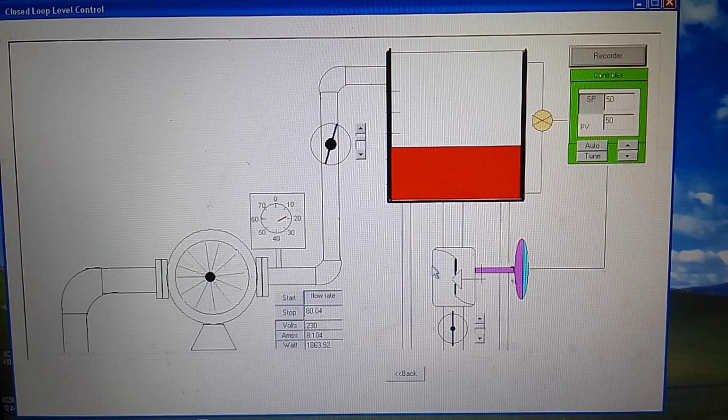But in this control system with the control valve and the controller, the level transducer produces an electrical signal and enters the controller, which calculates with the help of a control equation, here a PID equation, proportional integral derivative equation, and with properly tuned parameters, with the help of this control valve, it is controlling very smoothly. I hope you understood the advantage of an automatic control system.